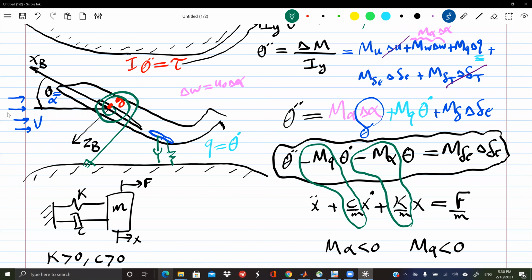Turn off the wind tunnel, so there is no air. No air means there is no spring and damper, because the spring and damper come from aerodynamics. Go and push this airplane on the tail or on the nose, away from the CG, and give it a disturbance. What will happen? There is no spring, no damping. It will go off, with nothing to restore it, nothing to resist.